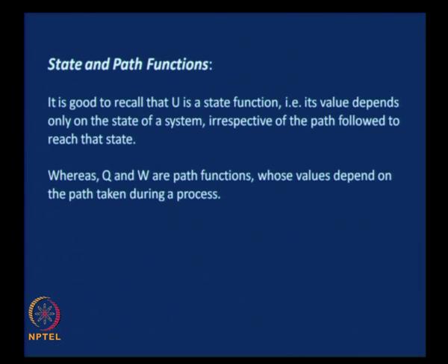Whereas the heat interaction across the system boundary and the work interaction across the system boundary are path functions whose values depend on the path taken during the process. This is a very important concept. In fact, we will be visiting this again and again, and at an appropriate time I will tell you an important aspect of this which helps us significantly in developing relationships in thermodynamics.